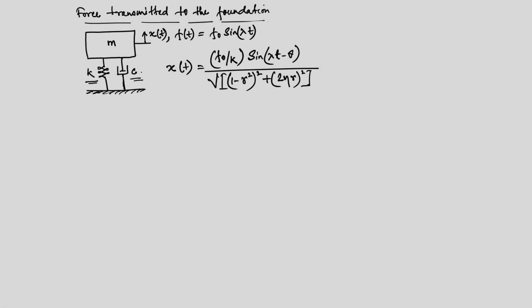That is the expression for absolute deformation this mass is going to experience. Now, it is also steady state response. Obviously, if you have a machine over a foundation, when you start that machine there will be a transient part, but as time progresses then obviously it will settle down with its steady state vibration. So, for the time being we consider steady state vibration.